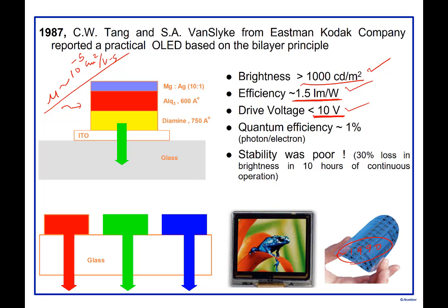All right. Now, the other thing that comes in: how is OLED contributing to the growth of flexible electronics? So you are seeing an emergence of organic light emitting diodes. Why? What are they trying to do? To make a display on glass. The idea behind this display on glass is that eventually this technology would be much simpler, because you're taking glass and depositing organic materials, which is much simpler in terms of fabrication than an LCD.